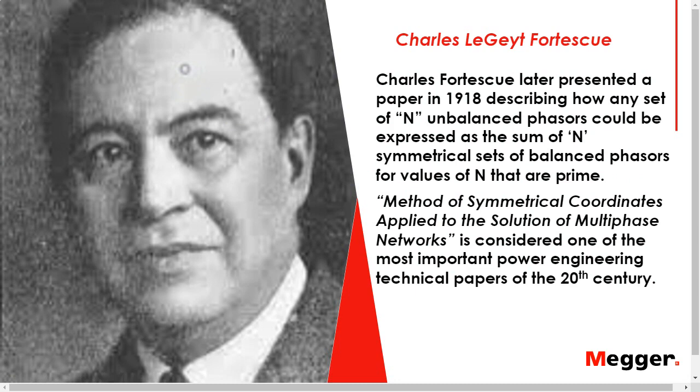Since this study originally began back in 1913, he ultimately presented this paper, Method of Symmetrical Coordinates Applied to the Solution of Polyphase Networks. He presented that paper to the AIEE in 1918, to describe how any set of n unbalanced phasors could be expressed as a sum of n symmetrical sets of balanced phasors for values of n that are prime.